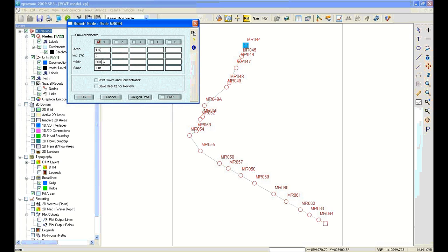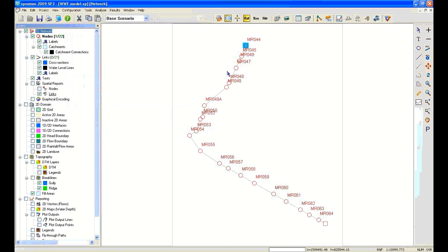Notice, though, that we use an extremely small percent impervious because we are trying to physically model something that occurs very complexly in the field. I mean, we've got water getting in from all these different areas, like we mentioned, in the pipe cracks, etc. And we want to somehow figure out a way to deal with that. So we put in a very small value, and we do this for all of these.